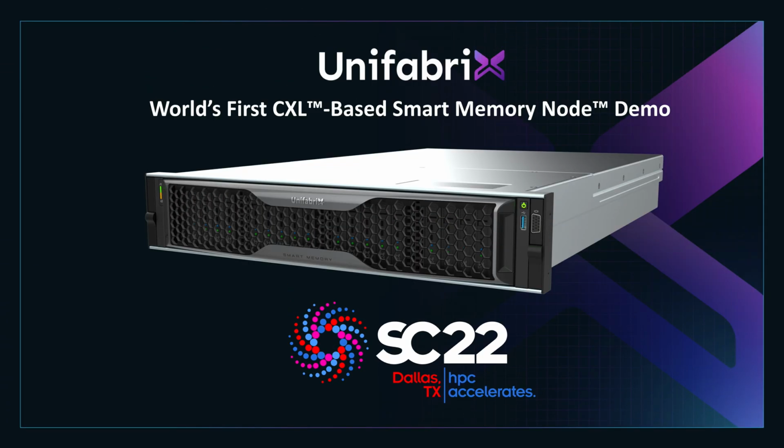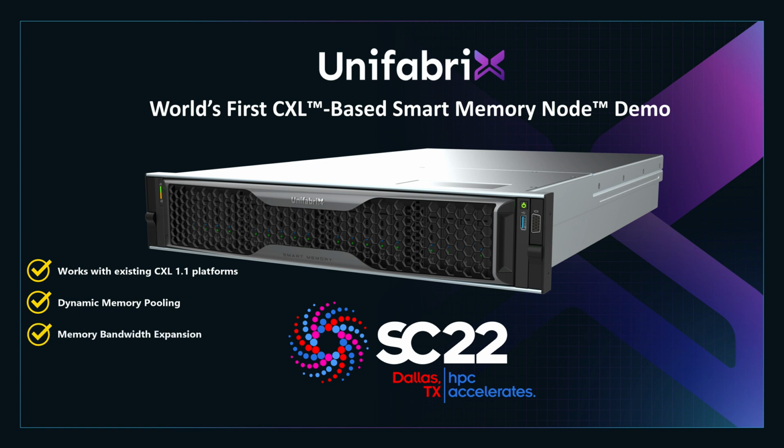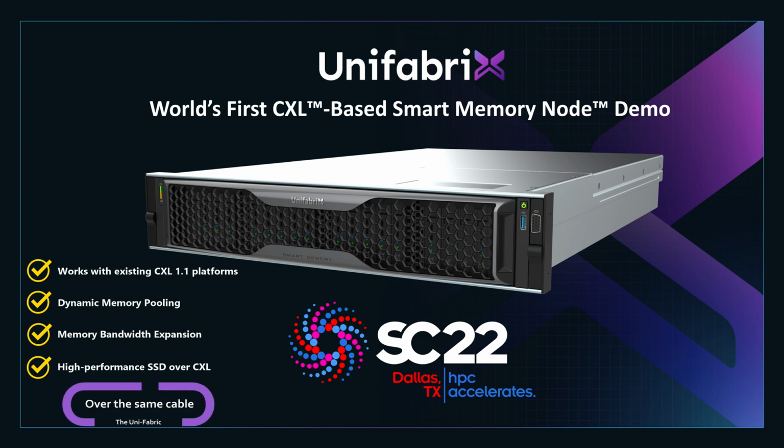Concluding our demonstration, UnifabriX Smart Memory Node enables unparalleled functionality with existing CXL 1.1 supporting platforms. These functionalities include memory pooling, enabling dynamically expanding and reducing the amount of memory exposed to the platform. Memory bandwidth expansion, enabling workloads to run faster by enabling underutilized cores to access additional memory bandwidth. Ultra-high bandwidth, ultra-low latency, standard block device exposed to the platform on demand, and plenty of additional features that will be exposed in the future. All are run over the same CXL cable or the same unified fabric.